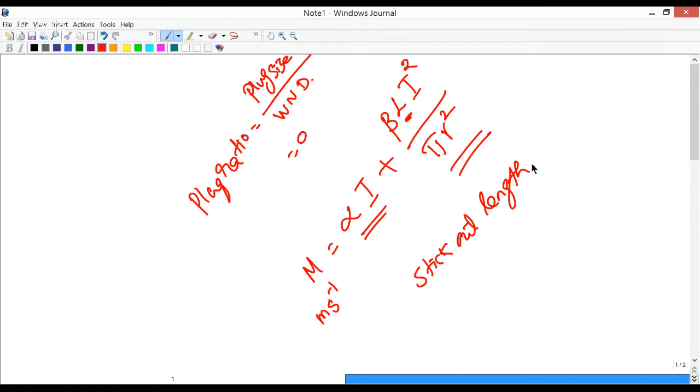In pulse GMAW, the heat input is generally much lesser than in constant current MIG GMAW, and the mean current is decreased. You will never get a jetting spray in pulsing because the current is not constant. Okay, so with that we conclude the first 3 assignments.